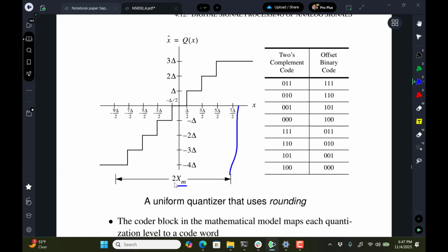And you've all coded in C before, right? So you go minus 2 to the, say, 16 over 2 for the negative values, and then you go to 2 to the 16th over 2 minus 1 for the positive. That's because you have one less level. But in the grand scheme of things, when you have a lot of bits, that one quantization level is minuscule, but it still does exist.